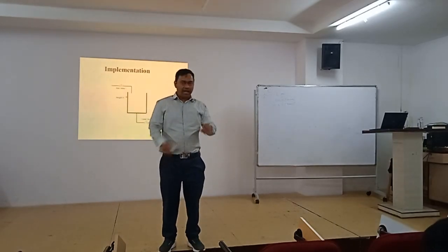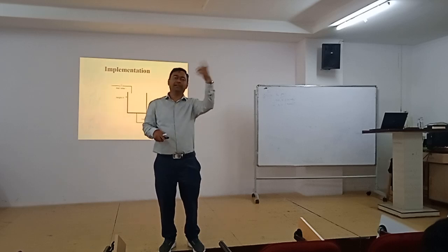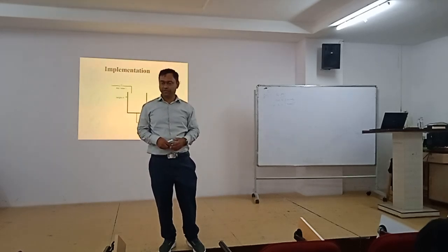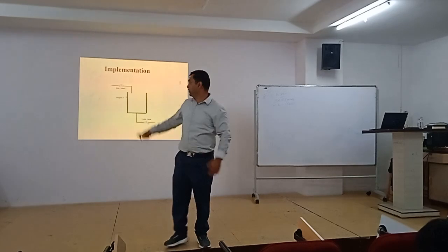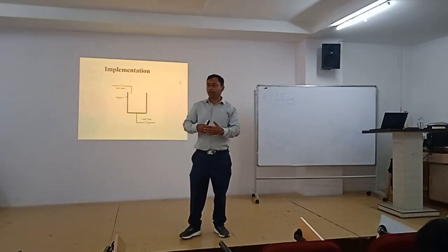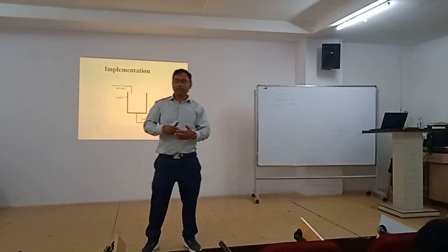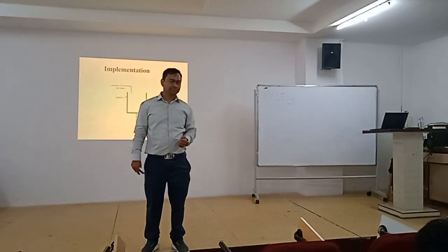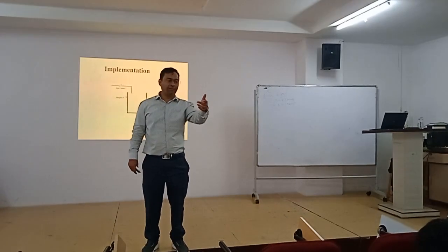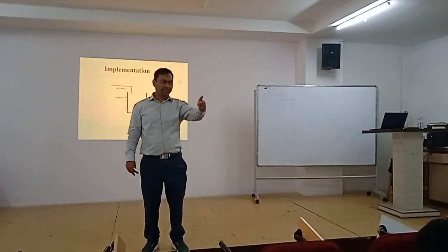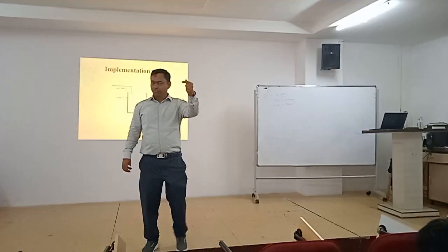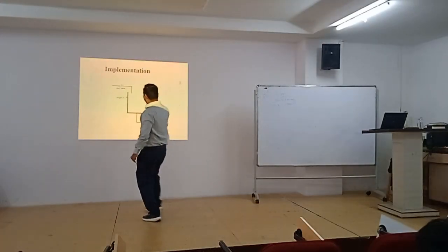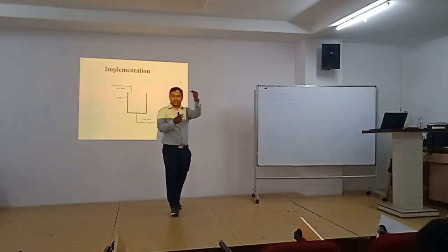Correct? And the controller is also receiving one more piece of information. Like when we were controlling manually, we also had one more piece of information. Which information? Position of valve. Actual height is what we want to measure. Set height we know, right? Set height we were knowing. So here also, this actual height will be compared with the set height.